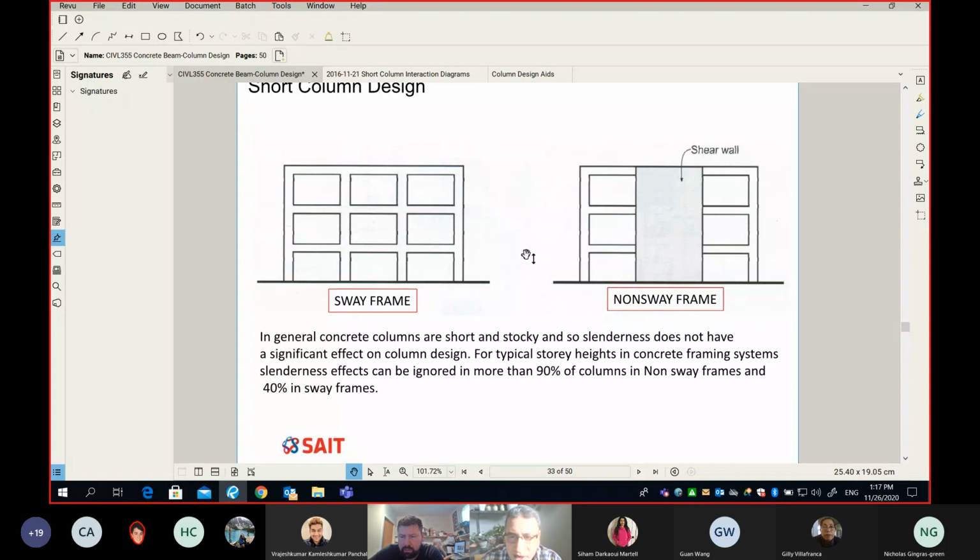The shear wall. Yes, the shear wall is the stiff element in your building that takes care of all the lateral loads. Because the shear wall takes care of all the lateral load, the columns in this case do nothing for the lateral load, except the exterior column if we support the glazing on the column. But if we simply support the column on the floor, it means the column will get absolutely nothing for lateral load. Hopefully this is clear.